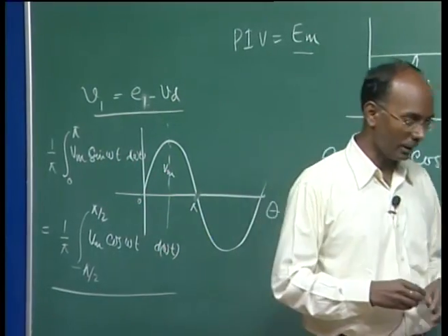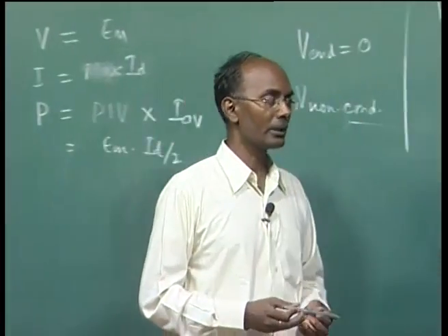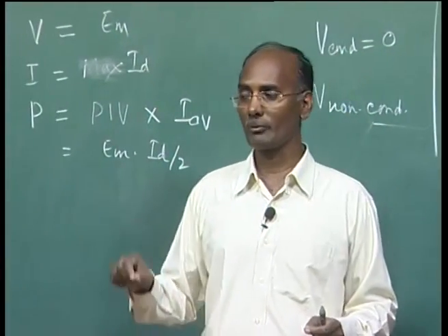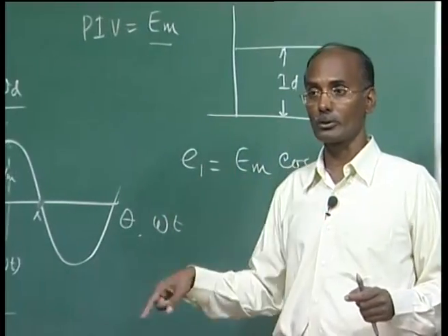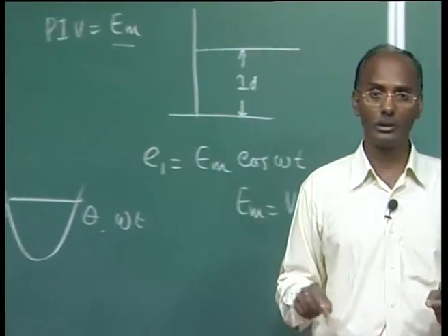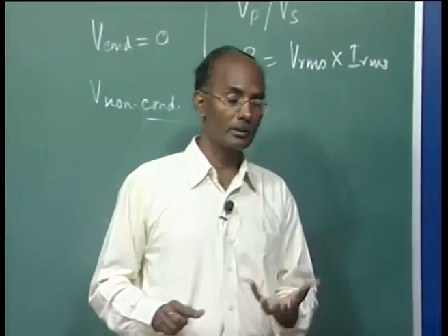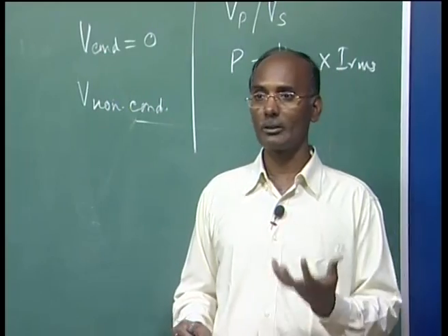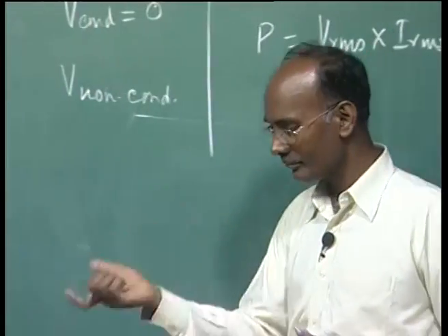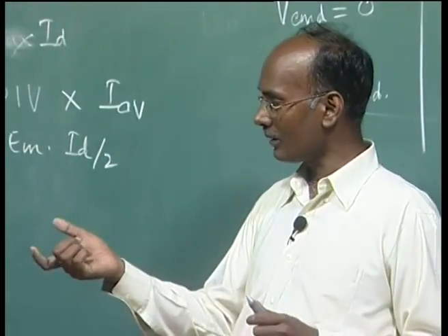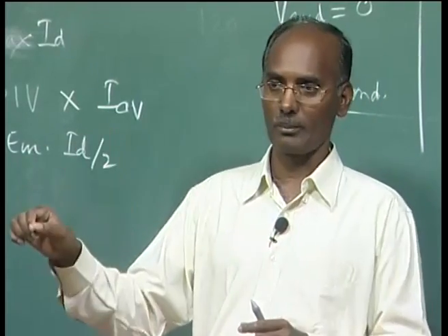But no doubt the actual transformer is designed in such a way that it should have a large leakage reactance, because when there is any short circuit in the converter circuit or on the DC side, the current will flow through the transformer and it should limit it. Especially during a converter fault, this transformer is the only safety measure, or safety valve, for protecting your valves. So practically we should go for a large leakage impedance, but in the analysis I take it as 0, because we assume the secondary side voltage is only transformed by the turn ratio, and that appears across your valve. There is no difference.